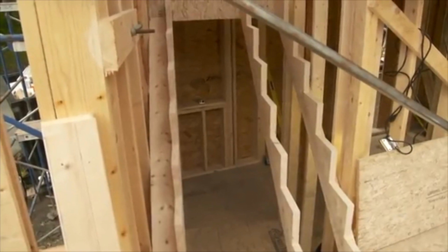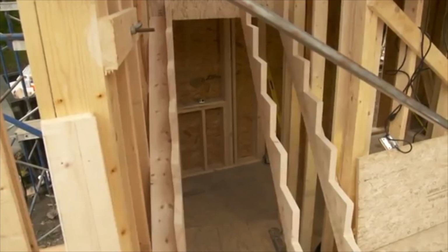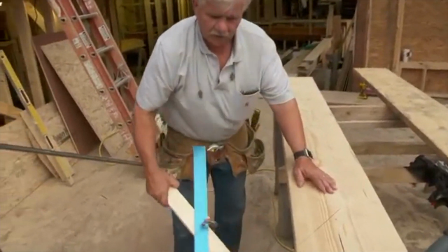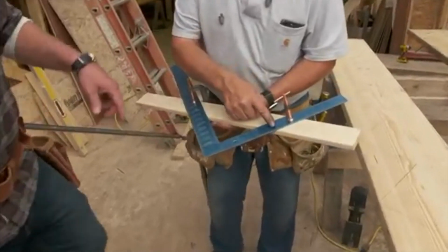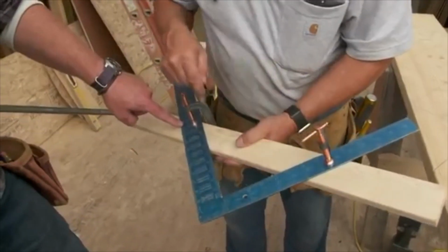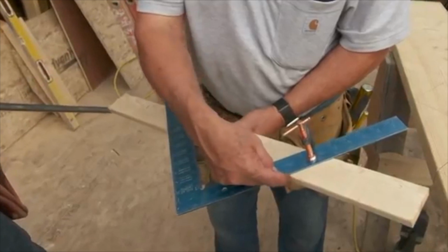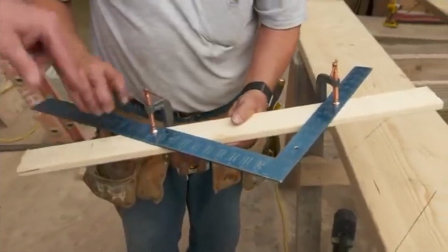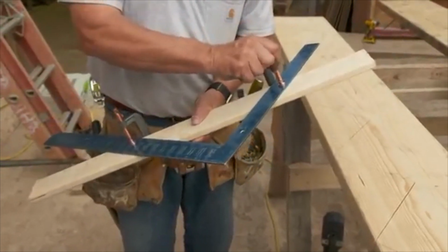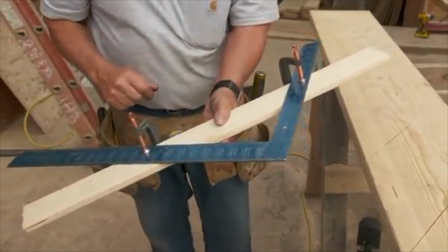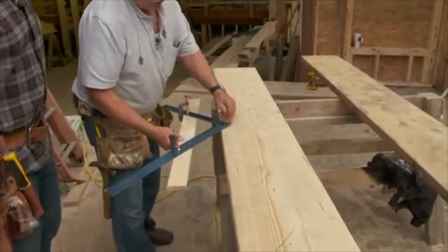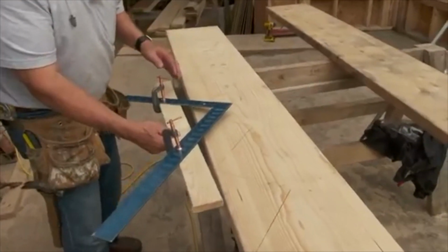Over here, I have one last stringer to cut. The important thing is once you calculate the height for the riser and the height for the tread, I take my framing square and I put those 2 dimensions on my framing square. Rise, run. Correct, and it's 7 11/16, goes right here with the edge of that, and 9 1/2 for the tread. You lock it in there, this is set up, and you can do it for every stringer, every step. They have all kinds of little attachments that you can put here. I like a long straight edge in case I run it along the edge, and maybe there's a knot, and those little tabs would fall in that notch.